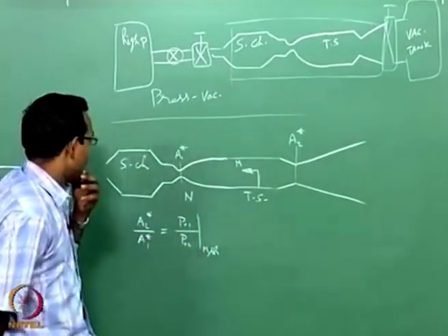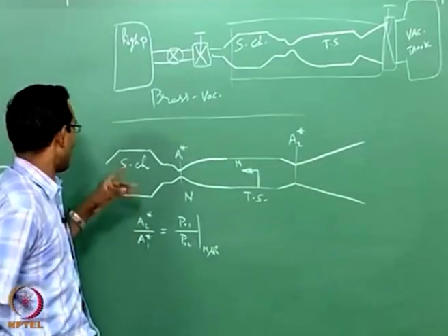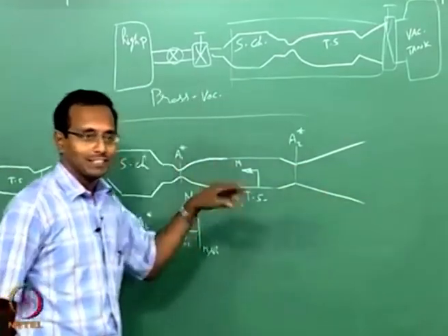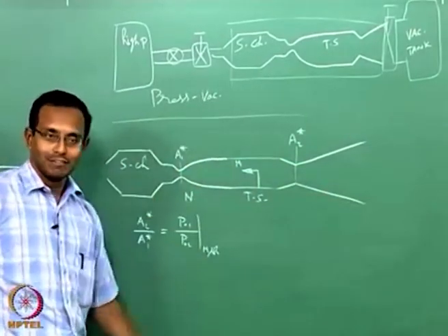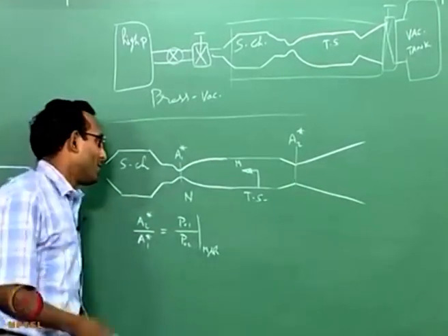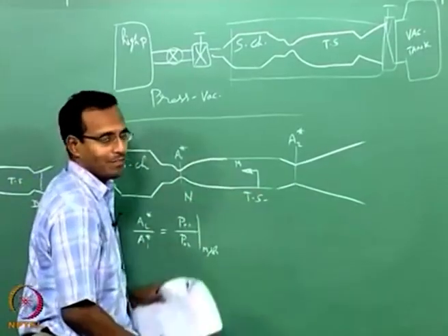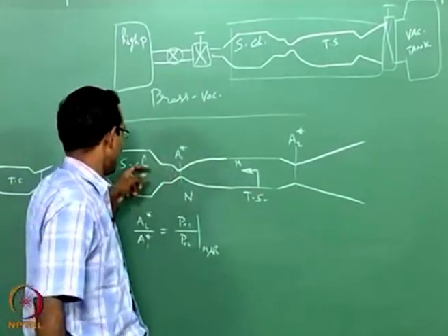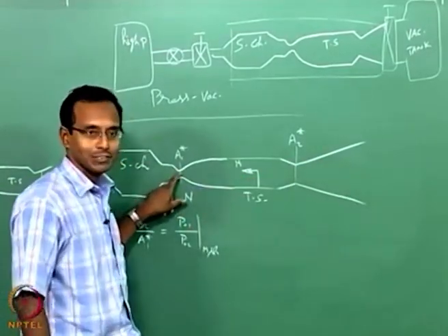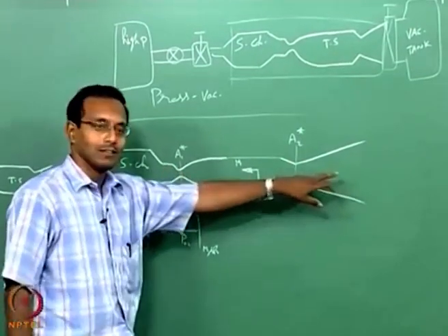Now of course I have to talk about starting of this tunnel. How does the tunnel start? I am going to apply P naught and I am going to apply a PB. We will apply it such that we know that the flow will start very nicely. So we will look at our nozzle flow problem again. What will we say? As P naught increases keeping PB constant, we are going to have fully subsonic flow all through initially, and this is the smallest area point. So this is the first point which gets choked. After that it will be choked and fully subsonic.